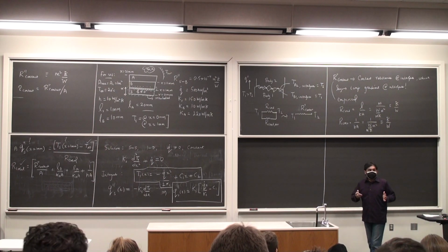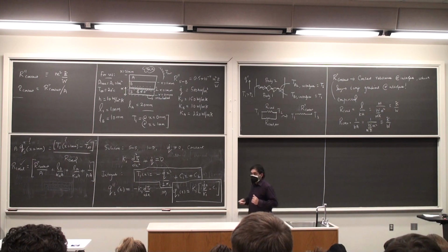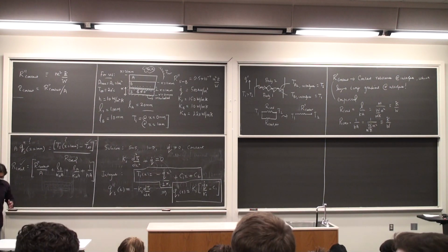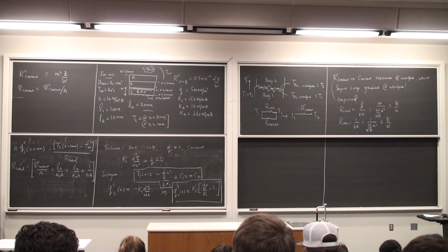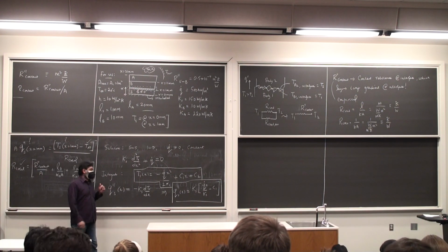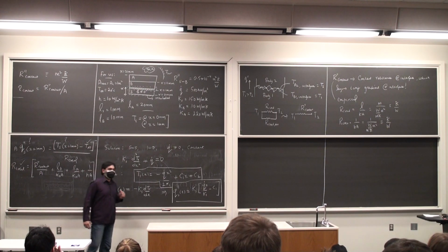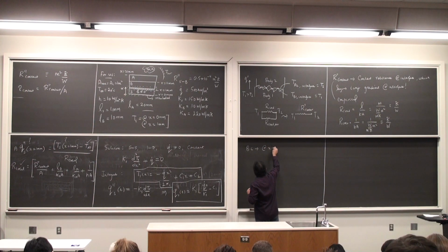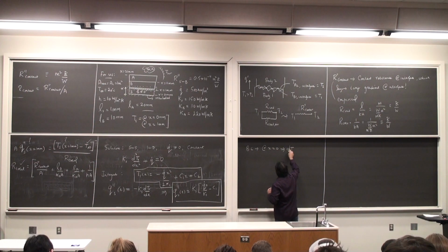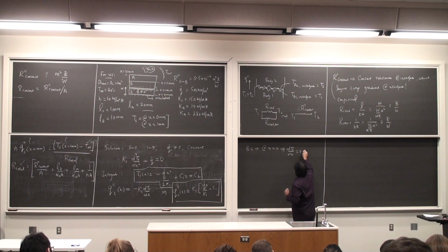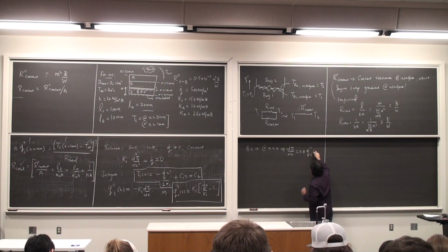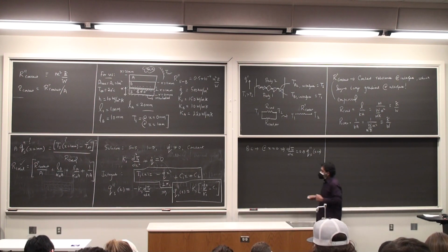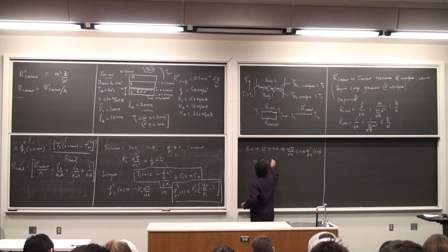Boundary conditions. Do we know any boundary conditions? Yes, sir? At x equals 0, it's adiabatic. At x is equal to 0, it's adiabatic, which automatically tells me that this character C1 is going to be 0. Okay? So boundary condition, it's insulated, and at x is equal to 0, dT by dx is 0, so q double prime s at x is equal to 0 is also 0. And so if I substitute, this tells me C1 is 0.